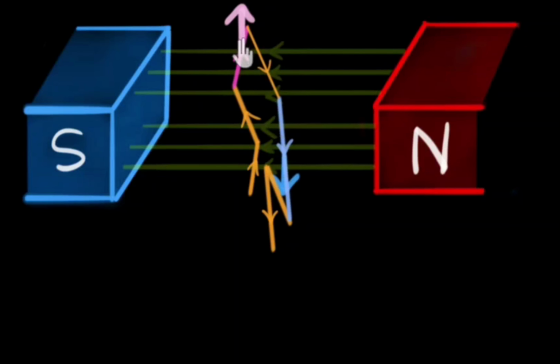The torque in fact varies with the variation of the angle alpha, which explains the principle behind the rotation of the motor. Let us do a stepwise analysis in this particular case. In step 1, initially consider the armature at its starting point or reference position, where the angle alpha equals 0. Since alpha equals 0, the term cos alpha equals 1, its maximum value, hence the torque at this position is maximum, given by BIL.